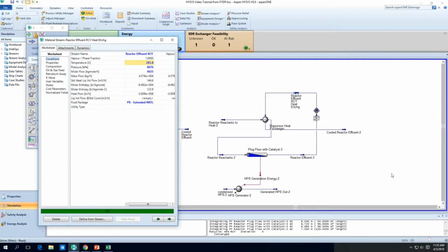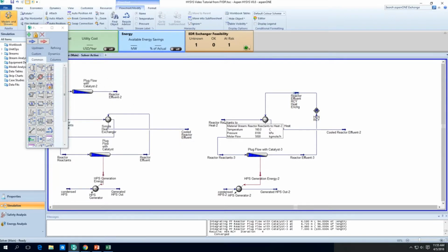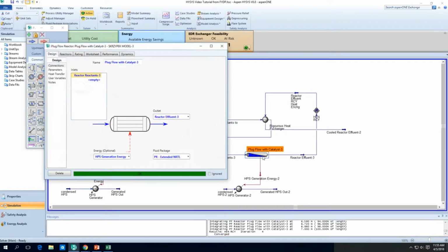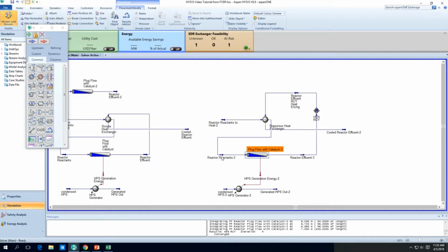And look, now it's converged again. So at 160 degrees C, it kind of does this thing. Apparently our outlet temperature has increased to about 284. That's just, I suppose, because of the way the recycle stream iterates itself. But the inlet stream should actually be lowered to about 250 degrees C.